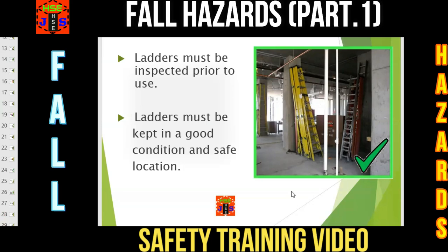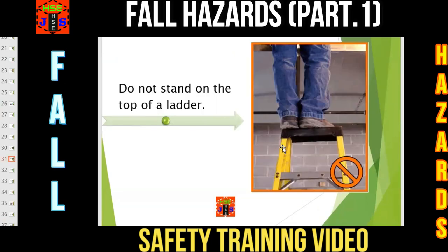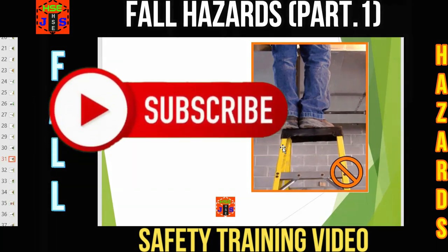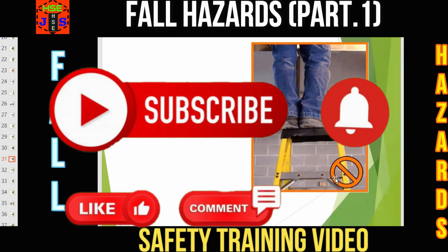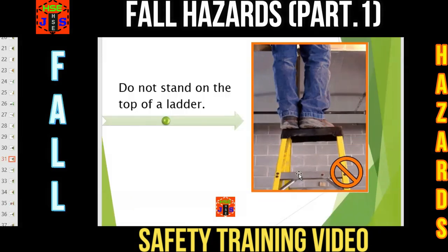Ladders must be inspected prior to use. Ladders must be kept in a good condition and a safe location. Remember, in any case, don't stand on the top of a ladder. Have a look. This gentleman is standing on the top of the ladder, and this work practice is not acceptable because it is totally unsafe.